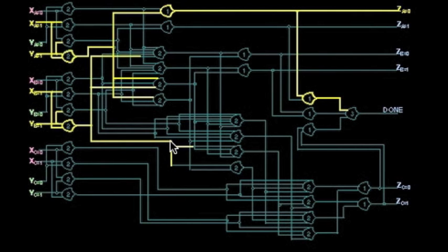Now this gate, a second input is transition to data. Now it's met its threshold, so it's going to transition its output to data, and that will propagate on. Now if we back up a little bit, we'll notice that it doesn't matter in what order these inputs were transitioned at this gate. This could have transitioned first, and this could have transitioned second. They could have transitioned simultaneously. And when they transition doesn't matter. All that matters is whether the threshold was met.